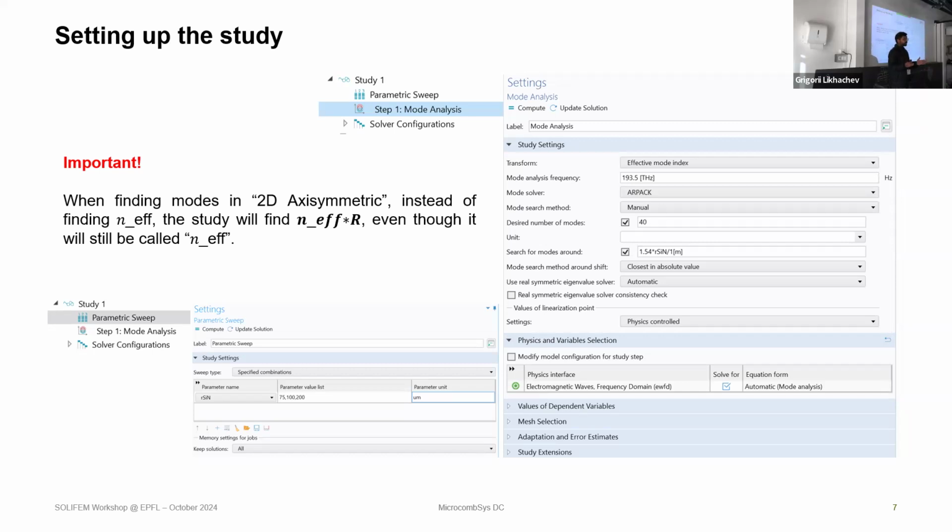So as you increase the radii, you will assume the losses should go down, because now it is fairly big, your bending is not too tight, your mode is not interacting much with the sidewall, so the losses are less. You should be clear here that the bending loss is simply calculated from the imaginary part of the refractive index. This has nothing to do with the scattering loss. Scattering loss is something different. That is a different subject, a different model is there to do the simulation. That also contributes to your intrinsic loss parameters, but we are not talking about that. It's just bending loss and purely because of the radii of the resonator.